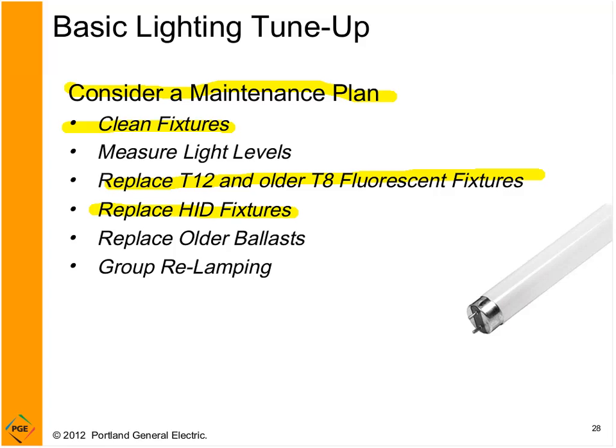HID fixtures are typically found in areas with high ceilings like storage bays, maybe big box retail stores. They're typically the round fixtures, and most HID lighting can effectively be replaced with fluorescent, and you can see some substantial energy savings, and there's typically some good incentives too.